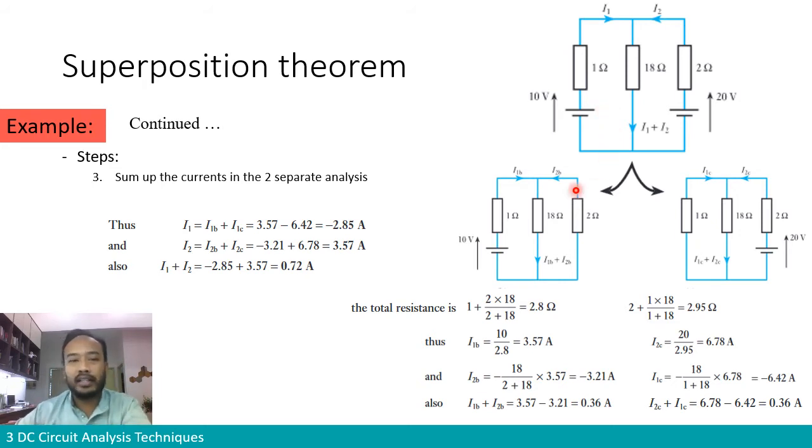So using the superposition theorem might be the simplest solution because you don't have to go through multiple loops and the interaction of current between different loops. It is just reduction of resistance into equivalent resistance and calculating your current using KCL or current divider.